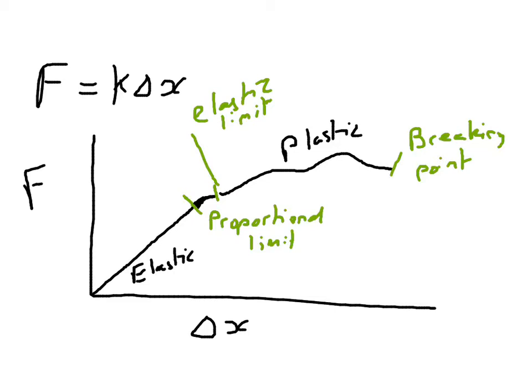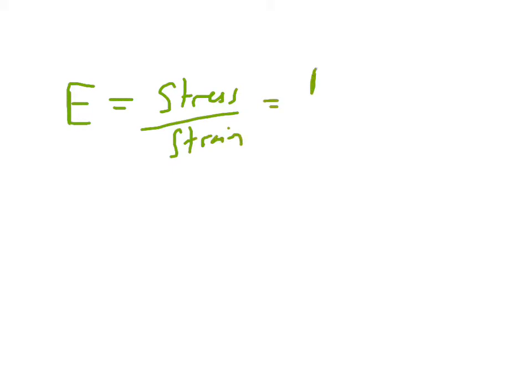What we're going to look at is some of the forces involved in that, because obviously they overlap with statics. The first thing you may remember from your A-levels is a factor called Young's modulus. You may have called it E, you may not. It is stress over strain, and that was the same as force over area, divided by the extension delta x over the original length.